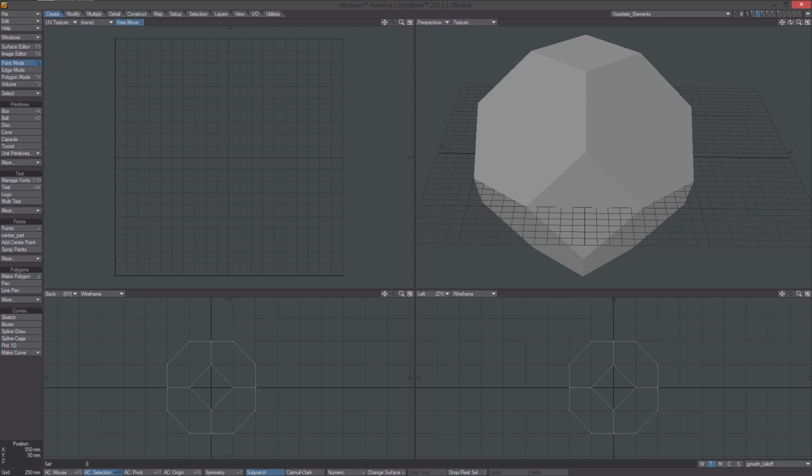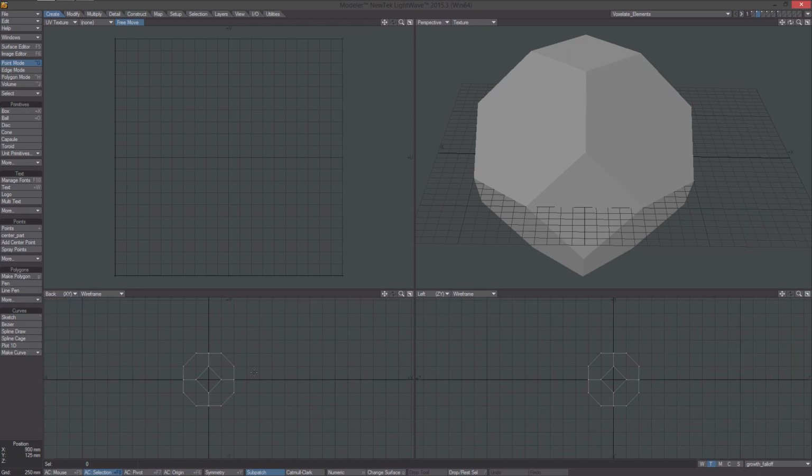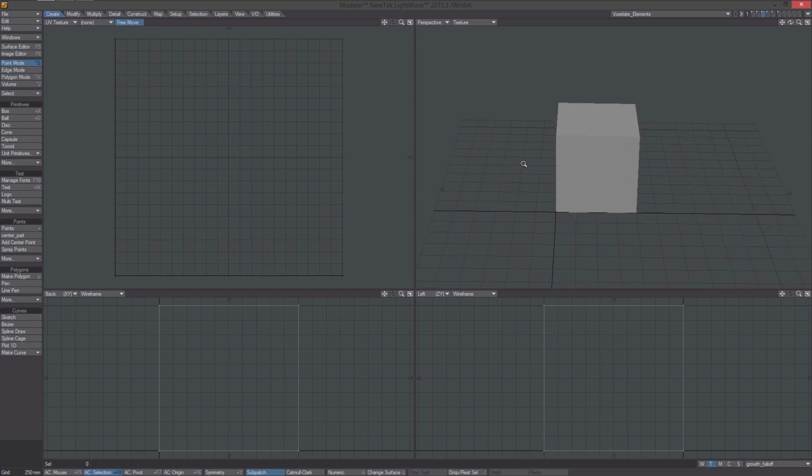It's set to be cloned at 1 meter, and I'm doing that because it'll make the setup much easier if everything is just one unit. For the next layer, it's just this box, and this is going to be the bounds for our array of truncated octahedrons. It's a way for us to visualize where they're going to be in 3D space.